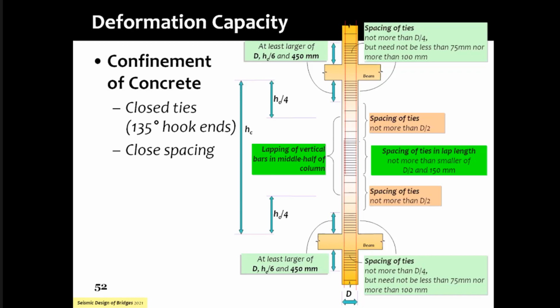If you take healthy columns, this will not happen. But there also, because it is displacement loading and the upper limit of displacement is not necessarily known to us, we can have a surprise earthquake with a larger displacement. We will say we will also design for plastic hinges at the ends of the columns. Fair enough. Then you put closely spaced ties at the top and bottom of the column.